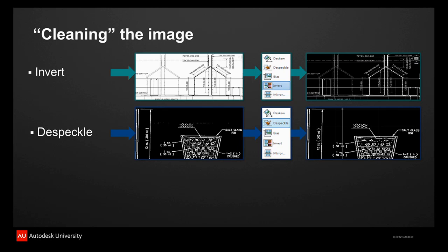So it's going to ask you to draw a window, basically. And this is going to indicate the size of the speckle, and it's going to then run through either a selection on the raster, or the whole raster image. You've got a choice by using parameters in the command for the area to analyze, and it will go and remove speckles of a similar size that it finds. So these will be isolated little pixels residing on the image.